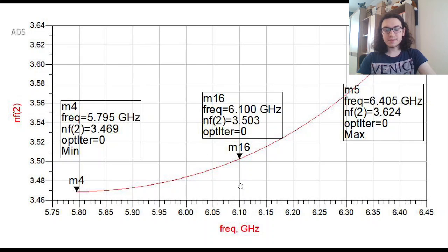In the center, it is almost 3.5 decibels. The thing is, our transistor is not suitable for an LNA, I think, but there isn't any other transistor that I can use for the LNA, and the minimum noise for one stage is close to 3.5, so it only added 1 decibel to the minimum point, so it's fine.